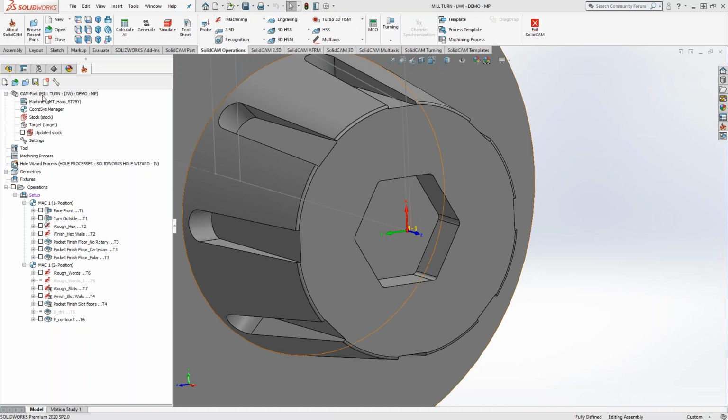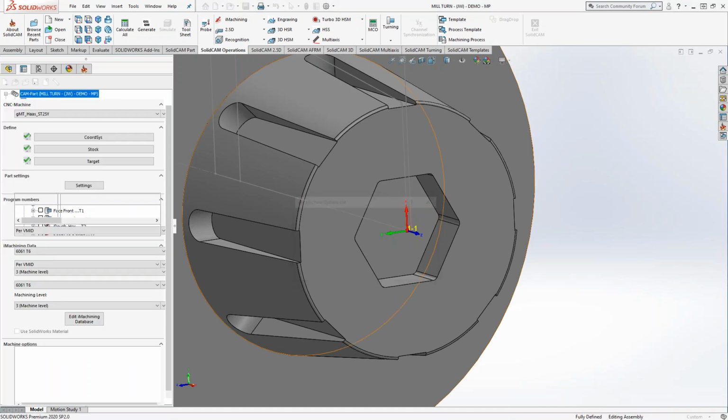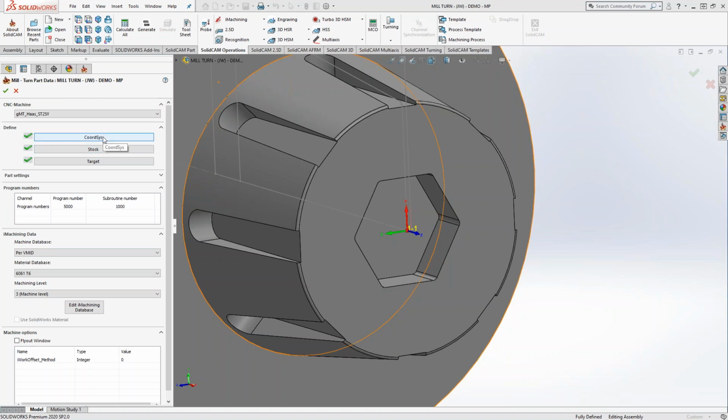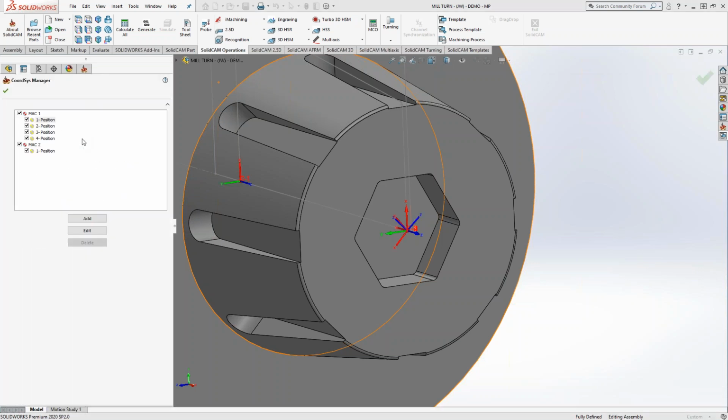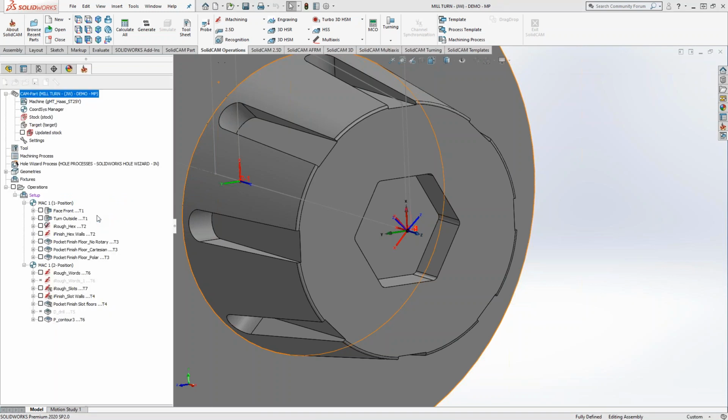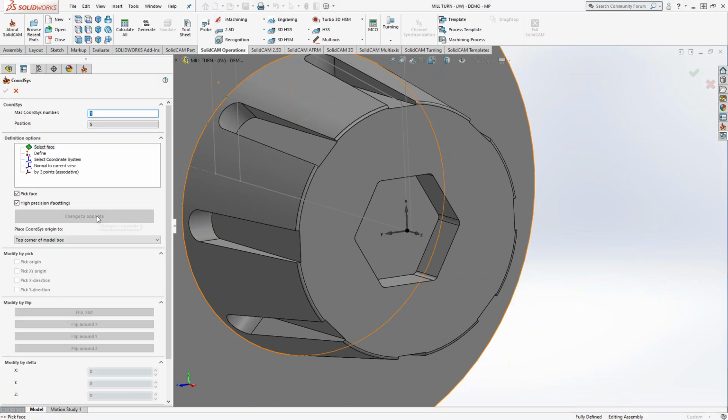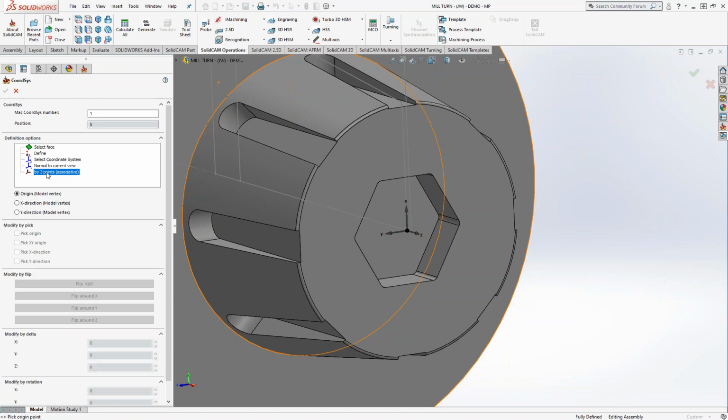Let's just go into this section here. So when you are first defining your part, you have to set up a coordinate system and you have to choose a post. So choosing a post, no matter what geometry you have, you're going to choose a post. But your coordinate system, you can define pretty much with any geometry you have on screen. So if it is a point cloud, you're going to most likely use something like by 3 points. You choose your origin, you choose an X direction, choose a Y direction. As soon as you have X and Y, you have Z, so you have your coordinate system.